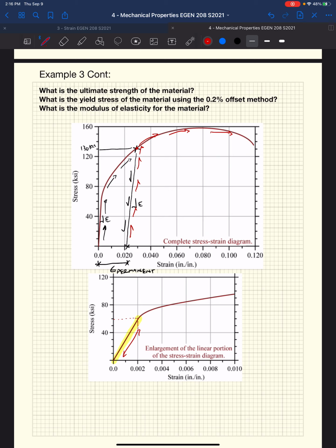We also know that the energy absorbed, or the toughness of our material, is the area under the curve. So we want this area to be very, very large. Well, in order to do that, we've got two options. You could either make a really tall and steep triangle or a very long and short triangle. What does that mean? Well, your modulus of elasticity is either smaller, so your spring isn't very stiff, but it can undergo a lot of deformation before it yields.